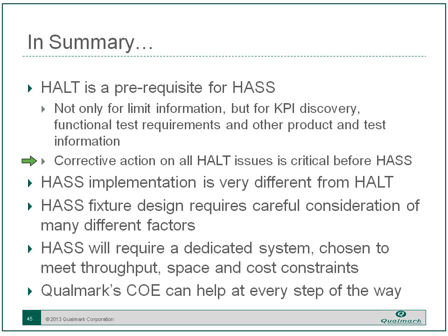If you find issues in HALT that for some reason you decide, I probably don't need to worry about it, it's going to be expensive, let's wait and see if it's an issue in the field, I don't have time, I'm going to miss my window, all those other excuses for putting off a fix will bite you big time when you start HASS, because if there is a distribution to that failure mode, it will be falling out in HASS in some significant fraction and not falling out in functional test because you need the stresses to make it happen, and you'll have arguments with manufacturing and production delays and all sorts of ugly things happening.